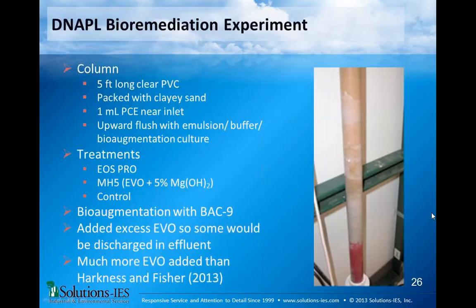One thing I have to add that's a problem with this that we have not solved yet is, ideally you'd just go out there one time and add all the magnesium hydroxide you need for the life of the project. The problem is you're adding a bunch of magnesium hydroxide before the hydrochloric acid is produced.